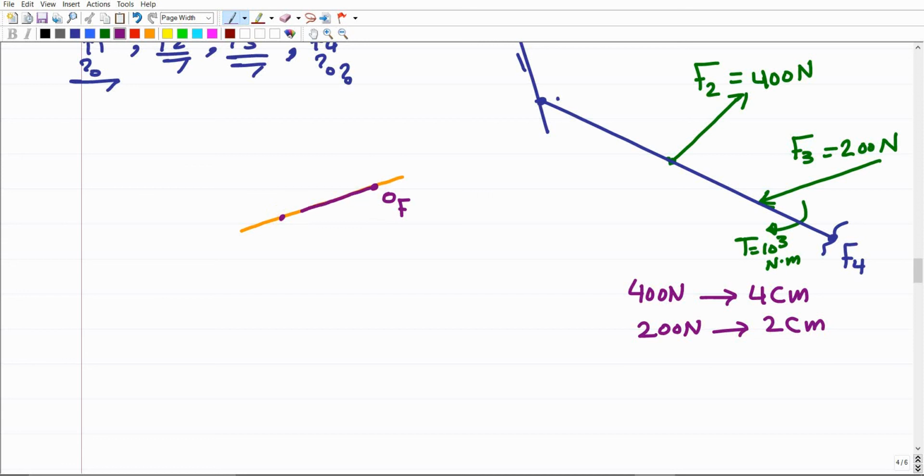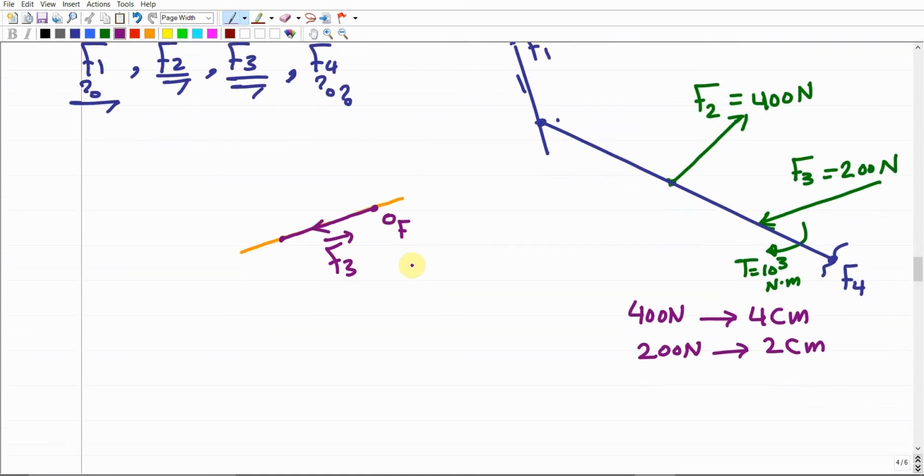Then you go over this line one more time to give you F3, and this is the direction of the F3 vector. Then from one end, you draw F2, as we explained in the three force member analysis. You start with either one of them. I started with F3, so from the end of F3 you have to draw F2. But if you started with F2, you start from the zero point, draw F2, and then from the end of F2 draw F3. Both options end up with the same resultant force.